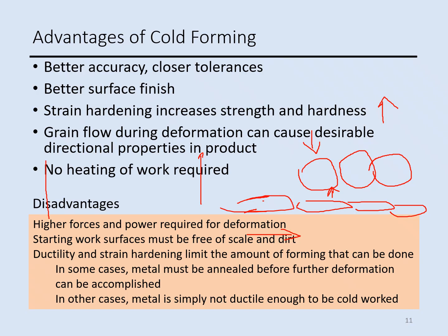But there are some limitations, some problems with cold working that we have to consider. First, because we are performing the process at room temperature, we need more force. We need higher force and power for the forming. And the starting workpiece should be clean.